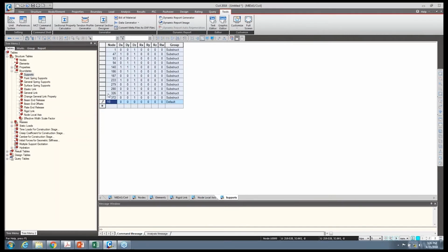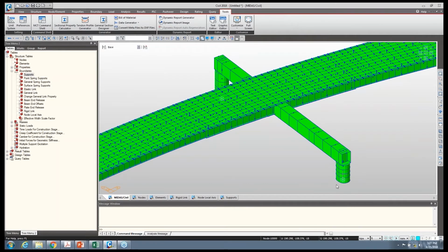And finally, what we're going to do is go ahead and delete the members that the MIDAS wizard created. And we'll do this real quick, just to visually show you. We'll go display, and we're going to go to the boundary conditions, and we're going to show the supports. So when I did my initial MIDAS wizard, what you'll see here is we set pier 1 as fixed, which is why you're seeing these supports appear at this girder line. And so what we're trying to do is make sure that we do not account for these, so we remove them from the analysis. We're going to go ahead and do just that right now. And they are sections 47, 140, 233, and 326. And that's just the case for this structure.